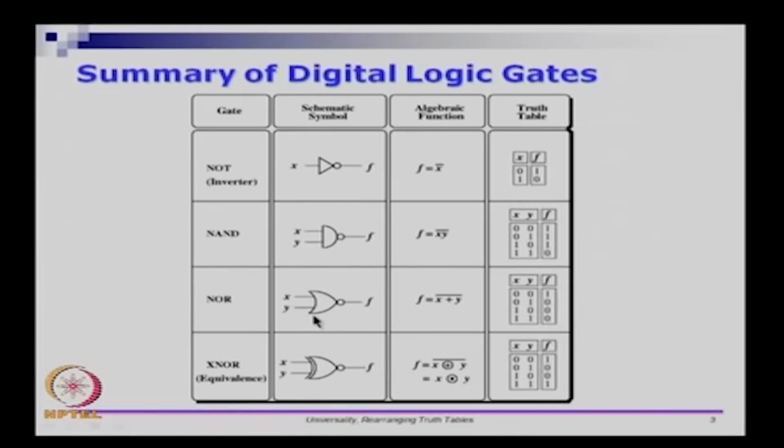The uncomplemented versions, namely AND and OR, actually need an inverter after the NAND or NOR. Take the physical implementation in CMOS, for instance, a technology used to make chips. In CMOS technology, NAND and NOR are something that you realize with basic transistors, with 4 transistors for 2 inputs, and if you want AND or OR, you actually put an inverter following NAND or NOR. Anyway, those are details that we can get into later. As of now, just remember the symbols.